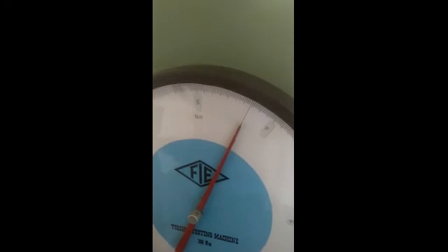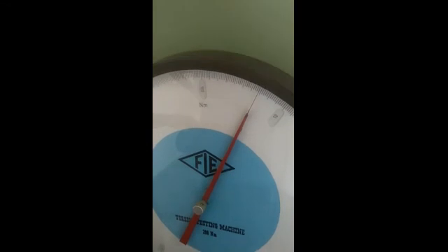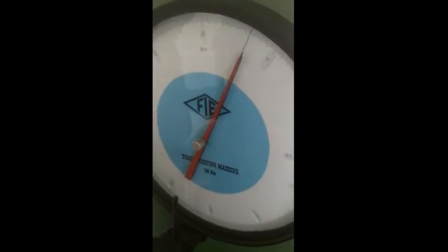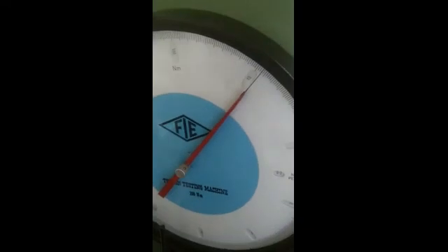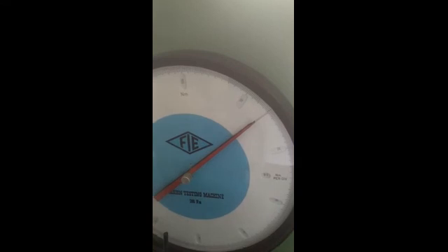We have to move manually. Once the upper yield point crosses, we can switch on the motor. We can switch on the motor until the specimen breaks. Next, we are taking the reading for 6 degrees. So changes will be seen in torque also. Next for 8 degrees. So at one point the needle will stop, it will not move further.